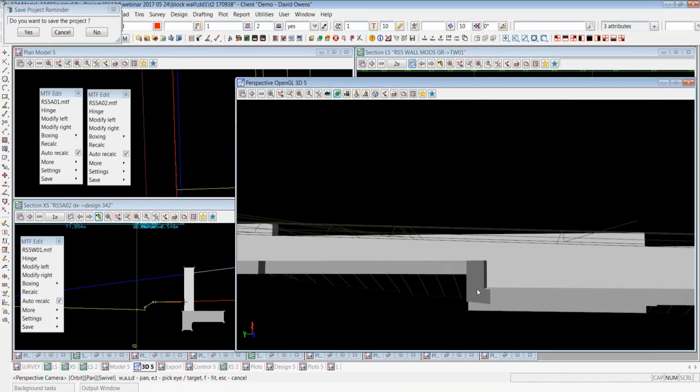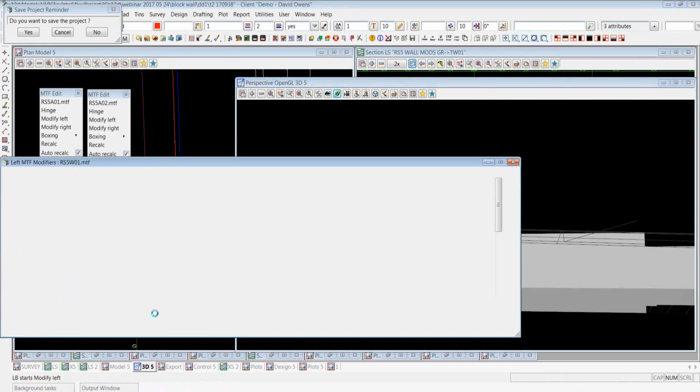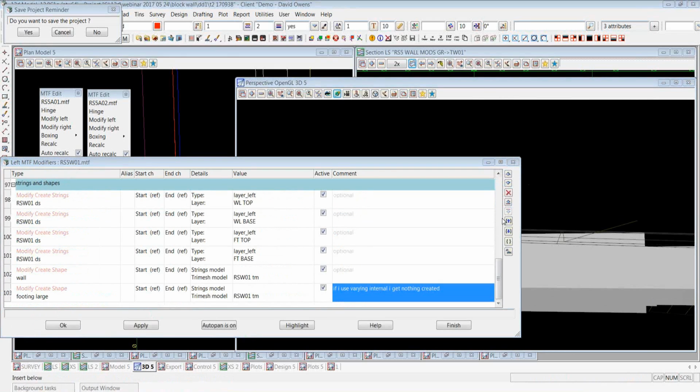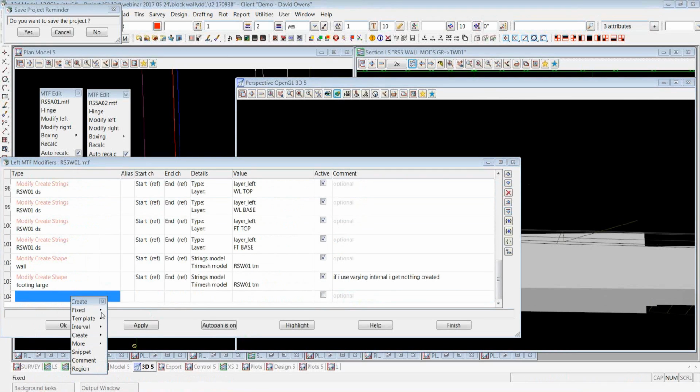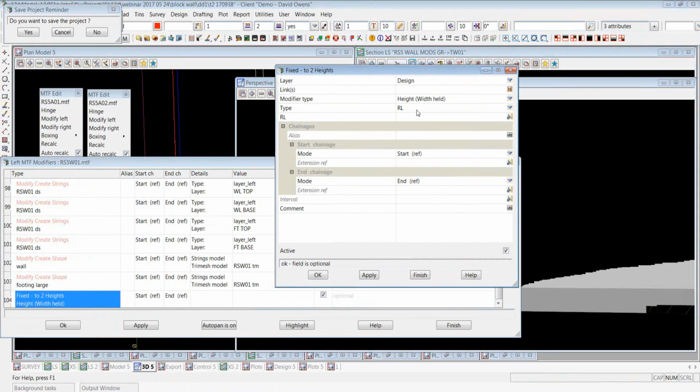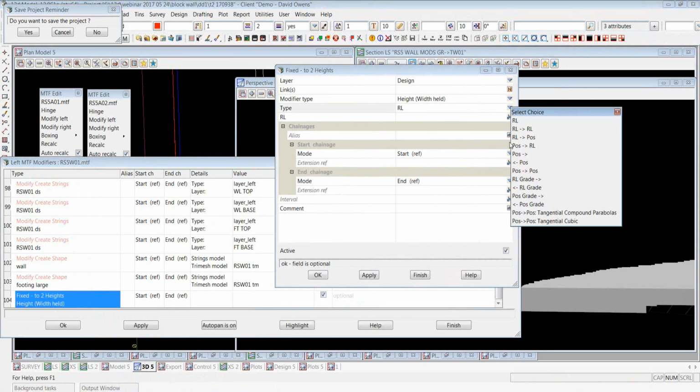But the basic modifier is using this concept of, I'll just bring the modifiers up again, and I'll just fire a blank one up rather than trying to read the snippet, because snippets are pretty ugly to look at. In this toHeights modifier, there is a type built into here where you can take the height at a particular position and push it forward.